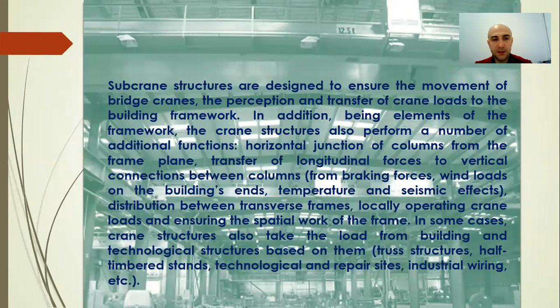So, subcrane structures. With a column pitch of 6 meters, beams have a length of about 5,950 millimeters, and the section height about 800, 1000 and 1200 millimeters. So the shelf width will be 550, 600 and 700 millimeters.